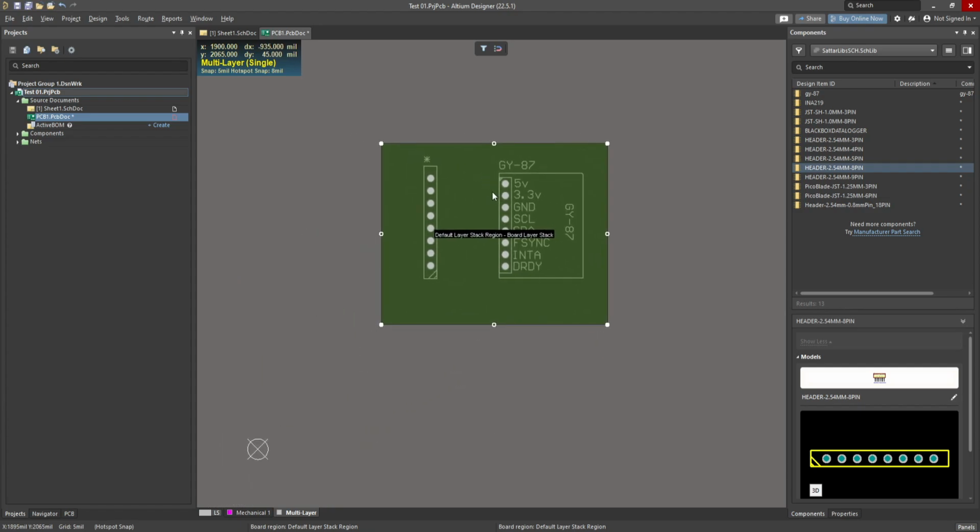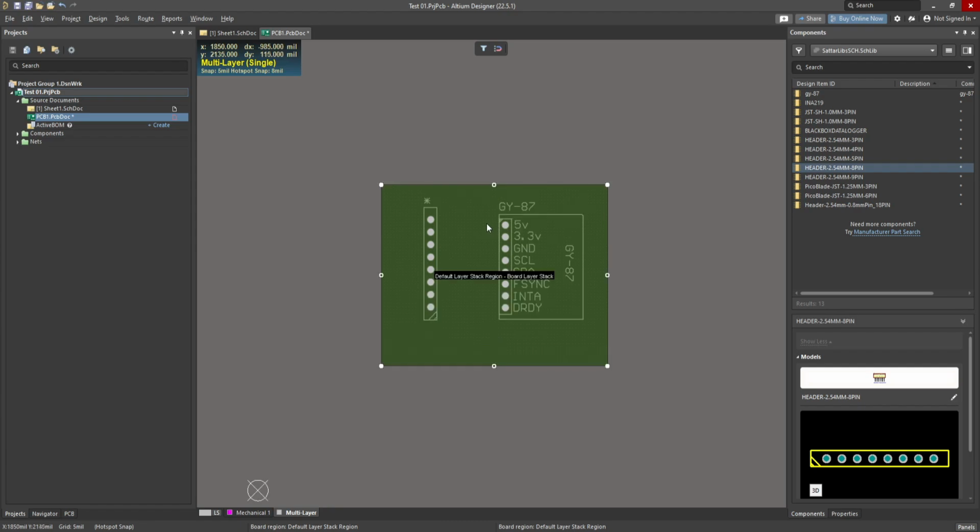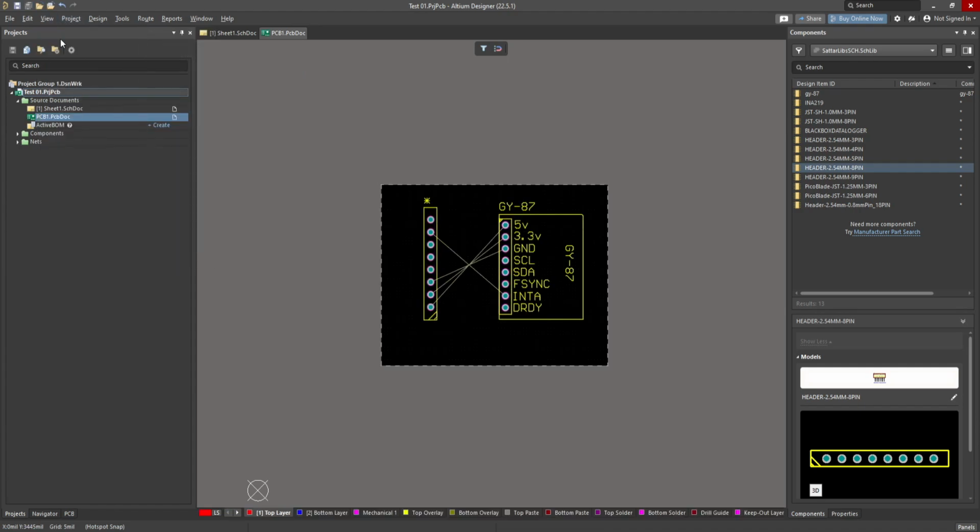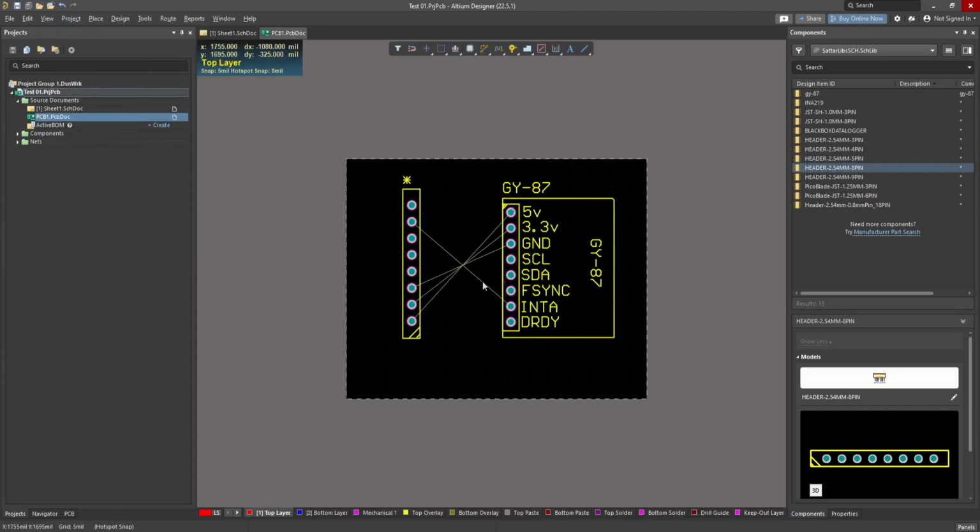There's another way through which you can make a board with the exact dimensions. I'll be putting the video for that as well very soon. So for now, let's keep this board simple and modify the board shape like this. Again, save it, project view, 2D layout. Now you can see that you have a tiny board with two modules on top of it. Now it's time to route.